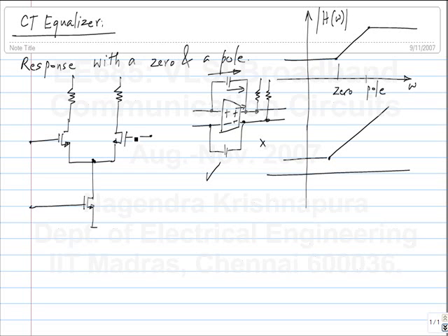I am only interested in making the gain of the amplifier dependent on frequency. So that means the capacitor has to play a role somewhere, and the simplest thing to do is to use degeneration, right? You use degeneration to make the gain of the amplifier independent of the active element, isn't it? So if you use degeneration resistors, Rs, and if Rs is much greater than the reciprocal of the GM of the transistor, the gain depends mostly on Rs, not on GM. Okay. Of course, this is frequency dependent.